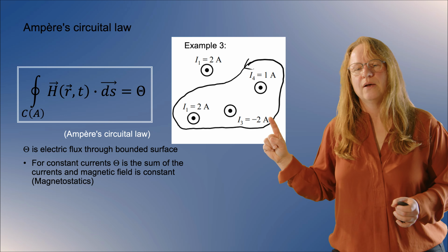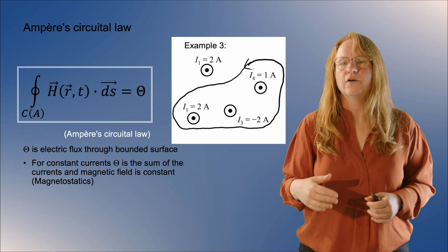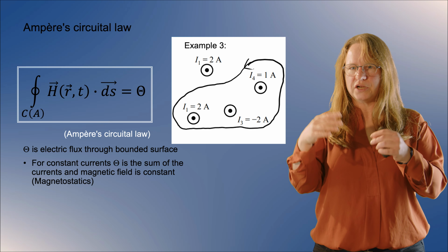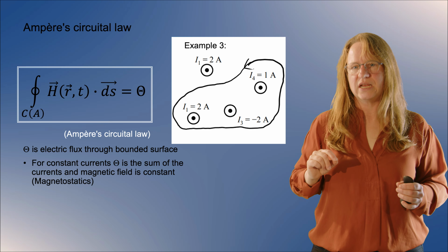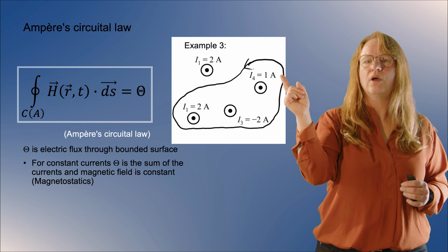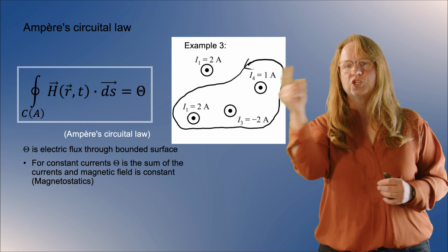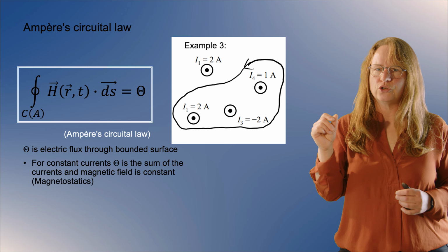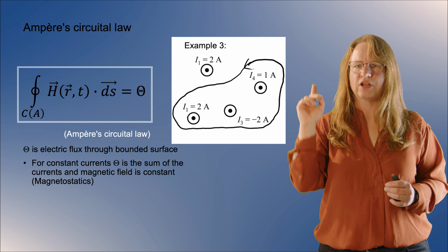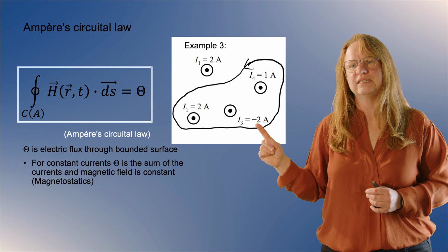What does that mean? Well, if you are defining currents, you typically define, first of all, a direction for the current I in order to give it some name and some orientation. But in reality, the physical current might flow back and forth along the conductor. It might change over time, going one direction or the other. So you don't change the notation every time. What you do is you change the sign.